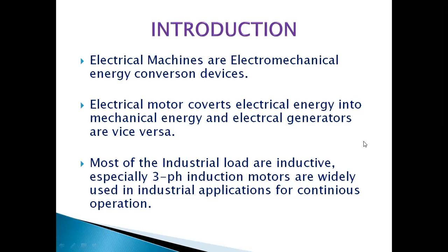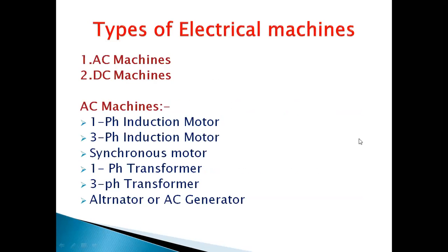But if you look at its whole construction and working, you will find there are some disadvantages of the induction motor. Like if we increase the load, its speed will decrease. So that is a disadvantage. Also, its starting torque is less. If we change the speed of the three-phase induction motor, its efficiency also changes. So these are some disadvantages of the three-phase induction motor.